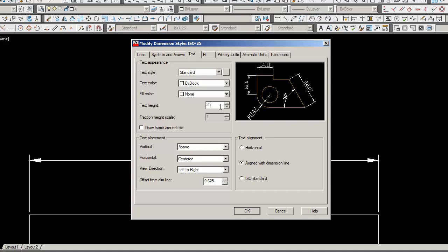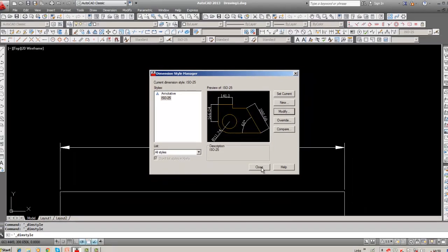That is, if the scale factor is 1:10 on a drawing, the text height on the drawing will be multiplied by 10 relative to the printed sheet. It is reciprocal. One we have to divide the actual size by the scale factor, and the other one is to be multiplied. So here we can make the text height 25, and this I will show you first.